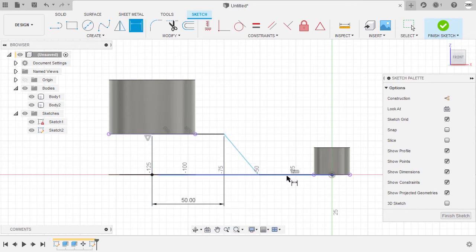Same with this line. So once more, we need to left click and hold, and this drop down will appear, and let's select our target horizontal line, which is this line. Move down, key in 40, hitting escape. Let's add a fillet to these corners.